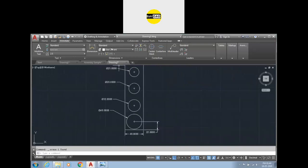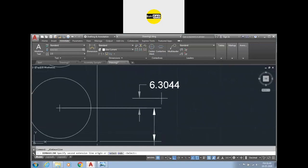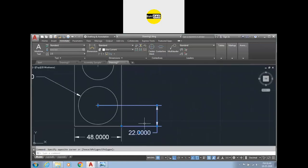So now we have an option here. There are two types: first is continuous, second is baseline. First I have created this shape. Now I am going to select the baseline type, and you can see that we have selected the baseline type, but I want the baseline to be this one. So the dimension should be defined from the base, from downside to upside.